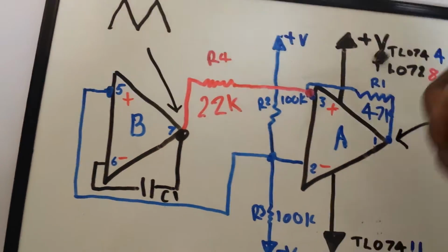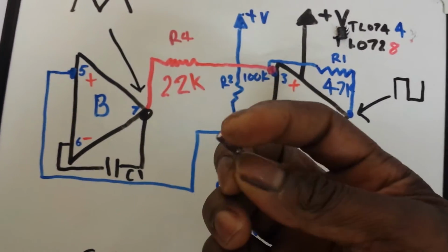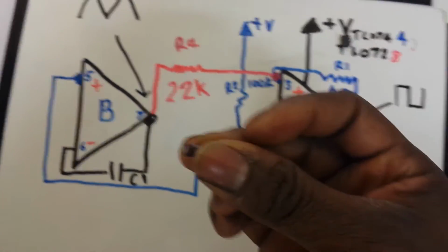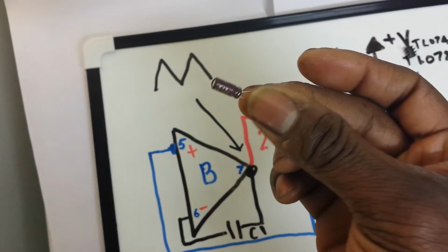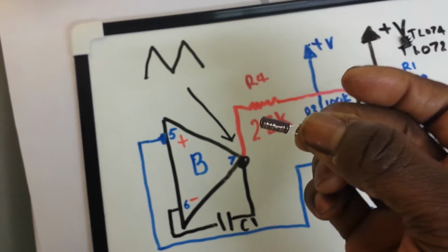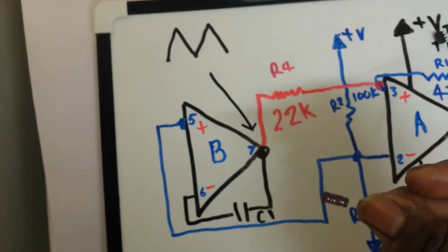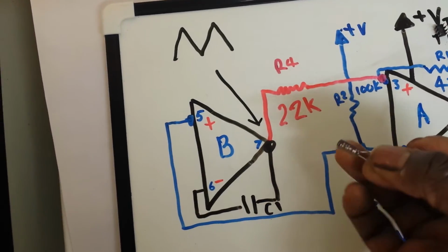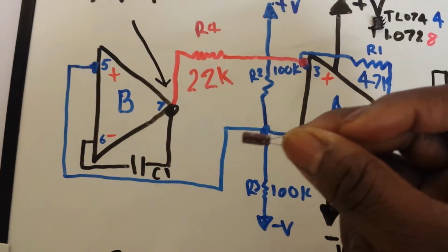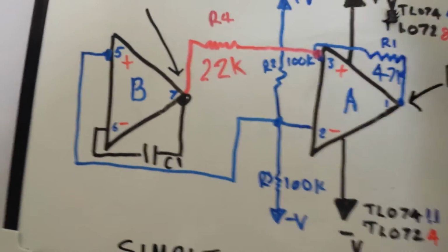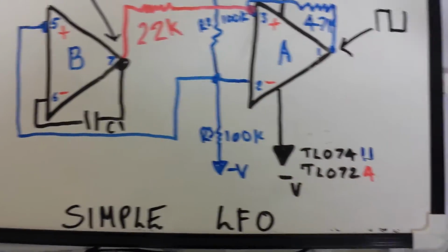Now if we're going to look at choosing capacitors, we can pretty much go for something like an electrolytic capacitor, because they will be in the microfarad ranges, so quite high values, which will give you a very low frequency if we go to quite the extreme lowest frequency response. If we go for something like a ceramic capacitor, I think the biggest value you can get will probably be something like a 474.